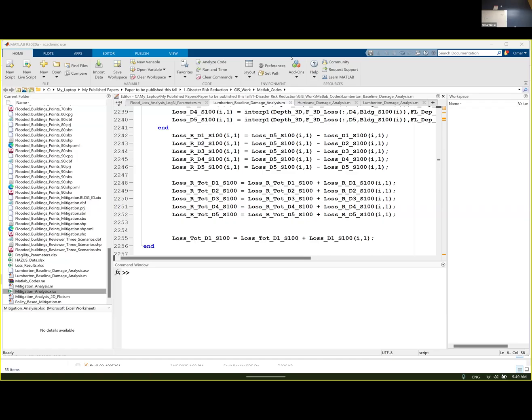So that takes us to the topic that there are hazard mitigations, exposure mitigations, and vulnerability mitigations. You can mitigate at different levels. When I use a levee, it dams the water and protects you, so it decreases the flood depth. Rather than having a flood depth of 5 foot, you're going to have 2 foot or something. That's a hazard. If you build a retention system that takes from the water that goes downstream, we are decreasing the hazard. If we use pumps, we decrease the flood duration. The flood duration is also a hazard itself. So all these are hazard mitigation measures.